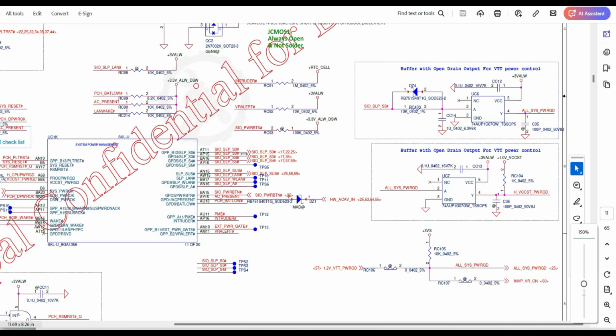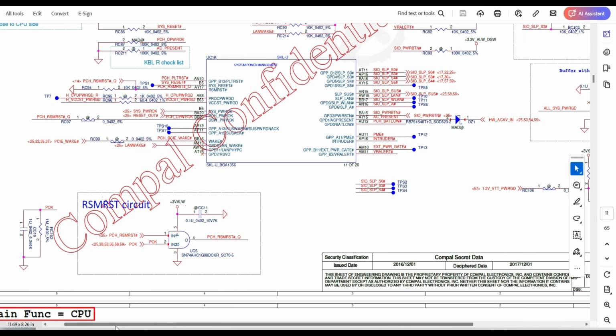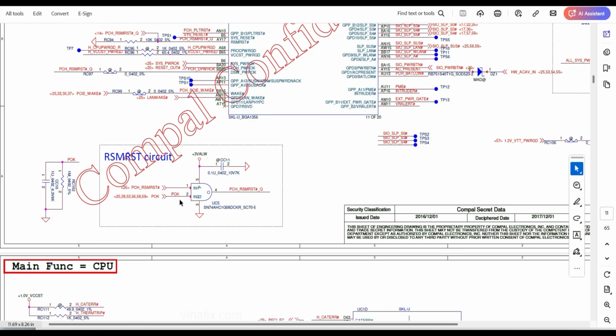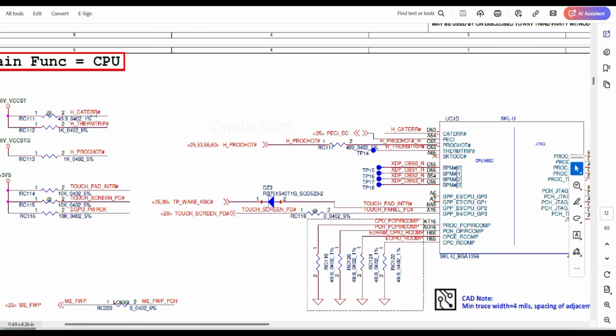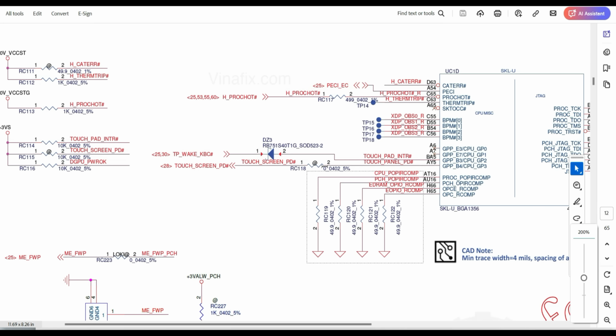Here, all resistors we can check. Here 0 ohms, maybe this same voltage will go here. And what is there here? Here is the pull down. See, this 3 volts you may get here, but here 100% 0 volts. Next here is the pull up, 1 volt will be here, and here 1 volt or maybe 0 because of ash. The size is 0402.